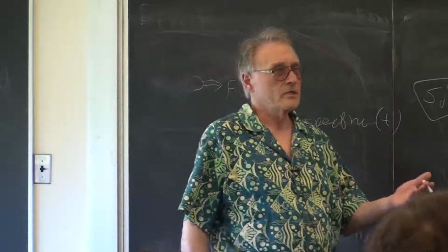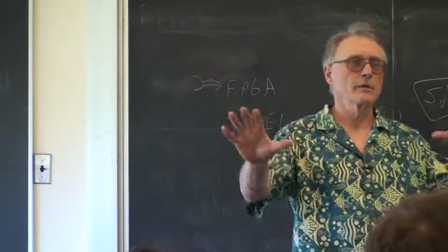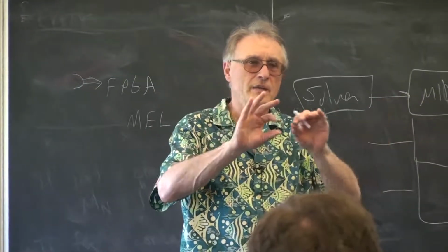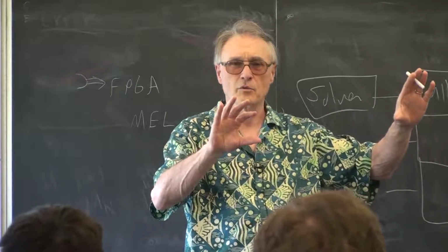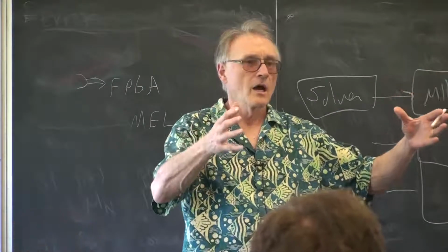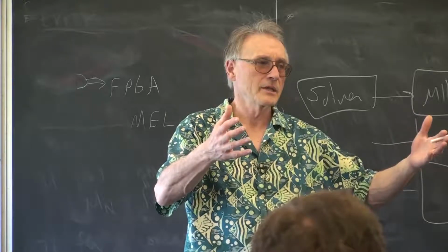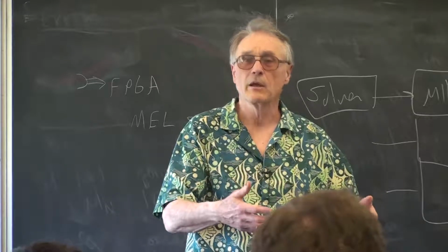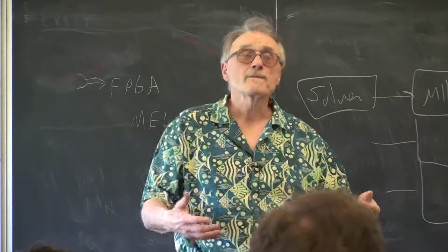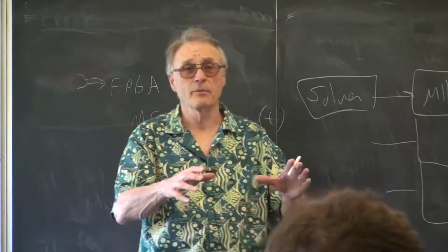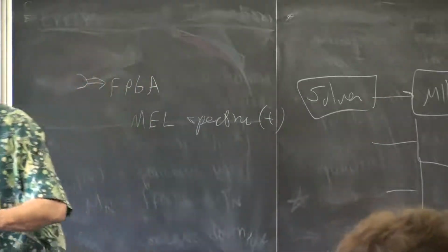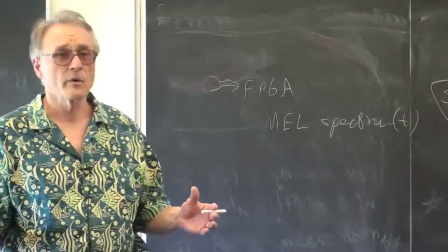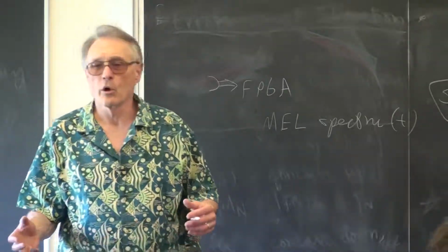So an ideal combination of things is where you have a big chunk of data running on one or the other side. It compresses down to a low-dimensional set of data and then expands on the other side back into some large problem. In this case, you're taking high bandwidth audio data, 48 kilohertz data. You're munching it down to a few Mel spectra a second, let's say 50 a second. So you're dropping the dimensionality quite a bit. And then you're sending that information over to the HPS, which is doing some big database lookup or least squares matching or neural network or something.